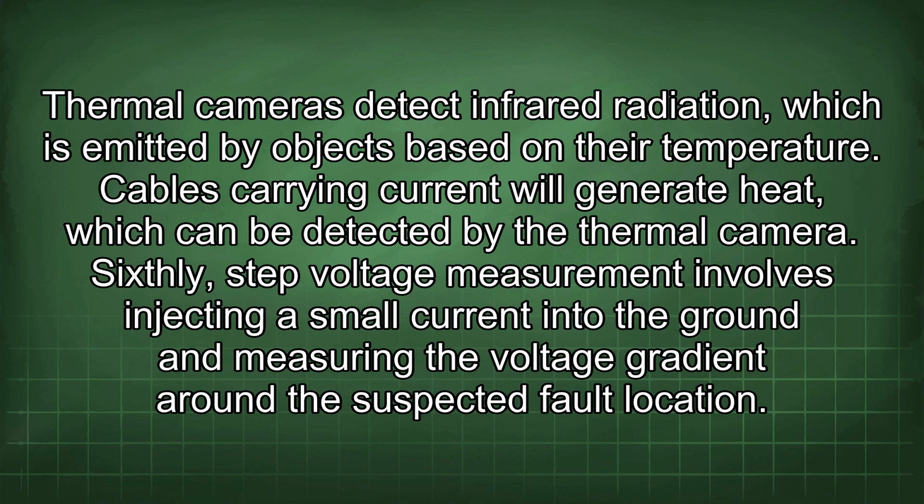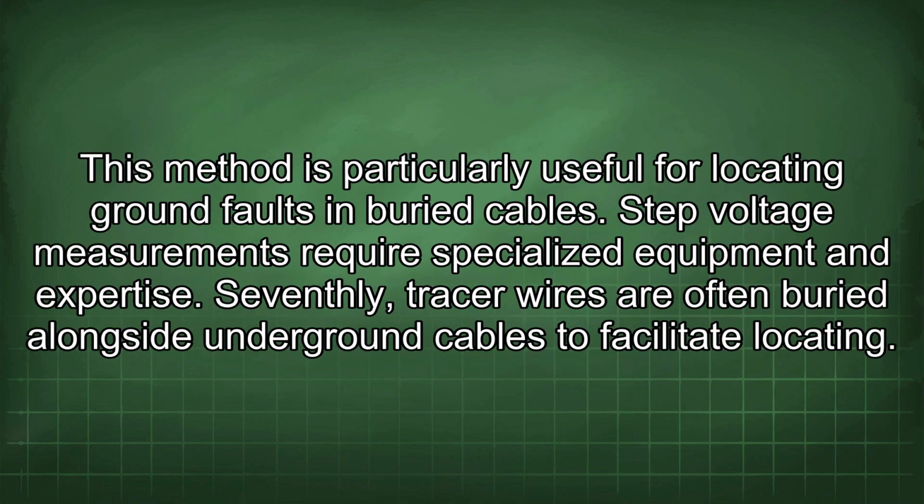Sixthly, step voltage measurement involves injecting a small current into the ground and measuring the voltage gradient around the suspected fault location. This method is particularly useful for locating ground faults in buried cables. Step voltage measurements require specialized equipment and expertise.